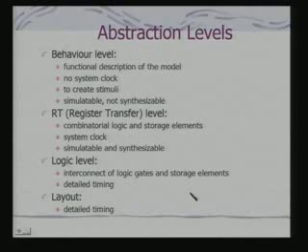And in fact, if we talk about the hardware, there are multiple levels of abstraction with which we can look at hardware. At the top level, what we call the behavioral level, which is a functional description of the hardware model, there may be no system clock. You want to create the basic stimuli, and this is simulatable.